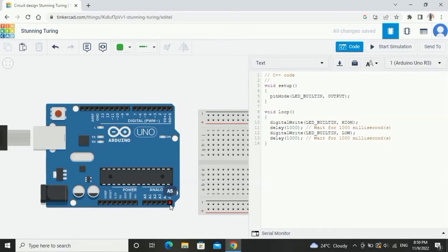And this is the analog. To read an analog signal, we have to use this analog pin here. And from pin 0 to pin 13, here is for digital input output. Normally they call this a GPIO pin, which means general purpose input output. The input range for the power here is 5 volts to 12 volts.